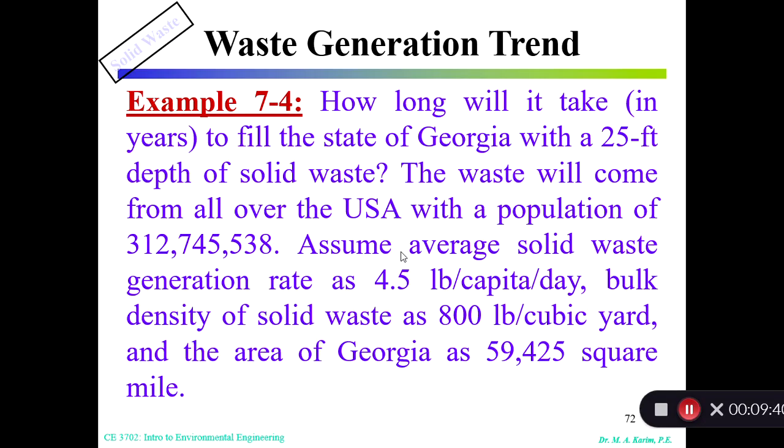I don't know exactly, I'm just assuming the number. If I say 2010 census, it would be 308,745,538. Anyway, assume an average solid waste generation rate of 4.5 pounds per capita per day, a bulk density of solid waste of 800 pounds per cubic yard, and the area of Georgia as 59,425 square miles. So these are the data that we have.